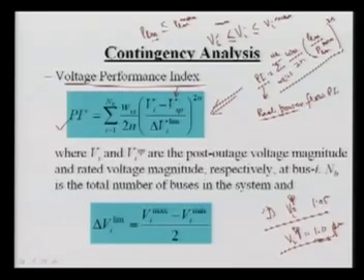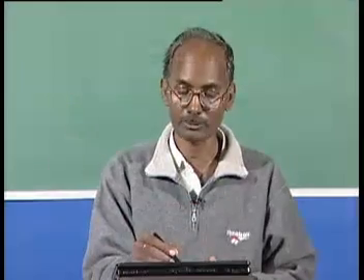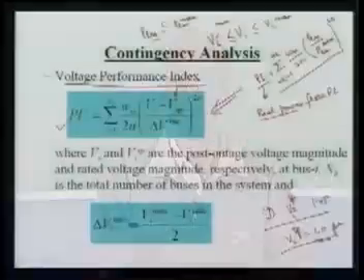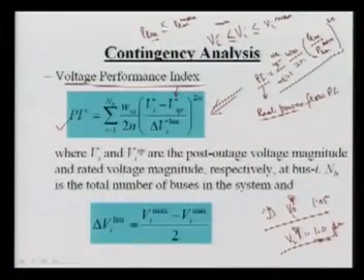We want that the voltage should operate at the specified value, so this will be 0 and will not add to the PI, because it is a summation over all the buses. So if all the bus voltages are equal to their specified voltage, then this value will be 0. Otherwise, if there is some deviation, this PI value will be higher, and that gives the relative severity. If this PIV is larger, I can say that for that contingency our system is most critical, and so on. Now again here we have the term omega V_i. It is also giving the relative importance of a particular bus.